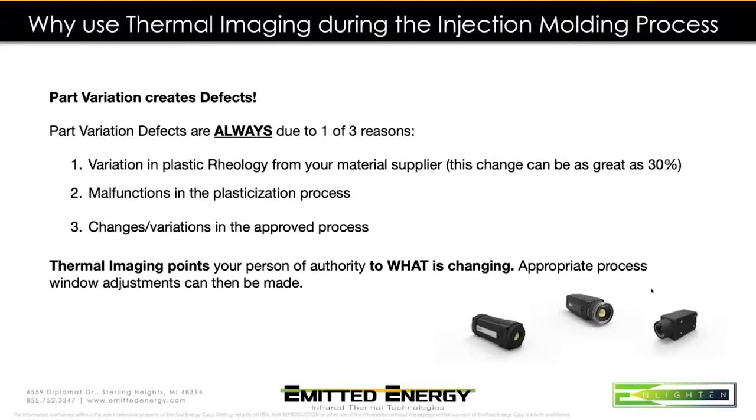Well, I can tell you that these materials are being made in reactor grades at something like 2 metric tons every half hour, and they're moving from one grade to another with less or more talc or whatever their offerings might be to their customer. The variation of that plastic, if you could take a viscosity curve on every single one, would be amazing. If you ever had an RJG system where you have two different pressure transducers at the beginning and the end of flow, that's a poor man's rheometer, and it can give you the viscosity of every single shot.